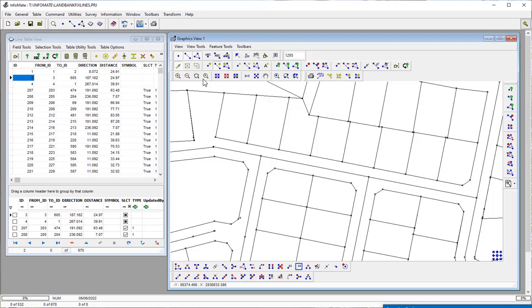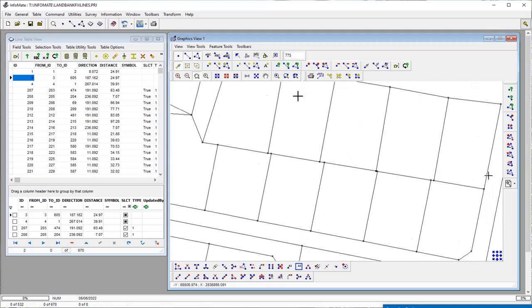So basically what this process does, it not only checks to see that there's a coordinate at each line intersect, it also breaks the lines up so that, for example, this line here goes from this point to this point to this point and so on. So it breaks up the line into its individual components. So this, in effect, facilitates the creation of the polygons automatically.